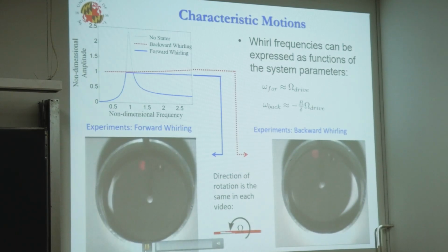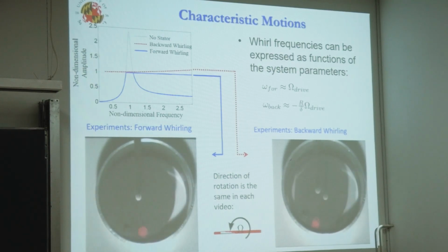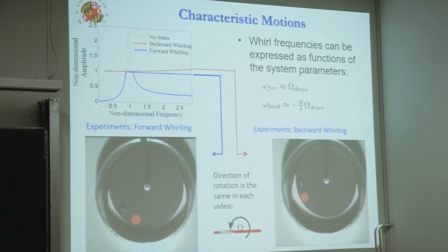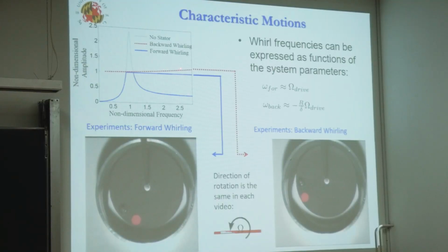If I took that rotor and projected it down to a Jeffcott rotor model and did another projection down to a torsional oscillator model, then you can plot this frequency response curve where, without contact, the frequency response would follow the gray lines and come down. With contact, you'll have additional branches. The red would be your backward whirling branch, and the blue would be a forward whirling branch. So you pretty much have two forward whirling branches.